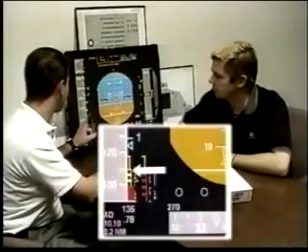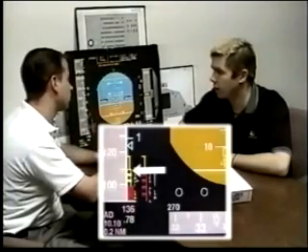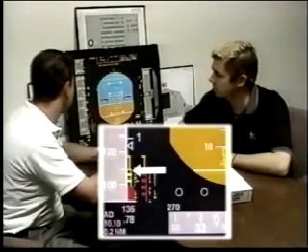If you come down through VLS, we get to the amber bumblebee portion of the speed tape. Describe to me the top of that. We call that alpha prot or alpha protection. And what are you commanding in alpha prot? Well, prior to alpha prot, when I move the stick, I'm commanding a load factor. When I get into alpha protection, I've got basically 4 protections that go on. We use the acronym ASAP, which is AOA is commanded, the speed brakes retract, the autopilot kicks off, and the pitch nose up trim is inhibited. We also are limited to 45 degrees back.